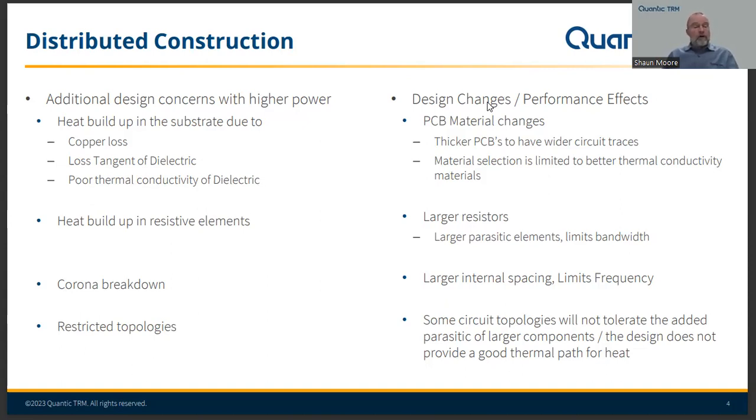I mentioned earlier, speaking about thermal buildup in resistors and Wilkinson power dividers, what happens there is we need to go to larger resistors. Larger resistors do have higher parasitic elements, which are undesirable, especially in a Wilkinson style power divider, for example. Theoretically, a Wilkinson power divider needs zero length between its nodes, and you do not want any reactance to ground from the resistive film.